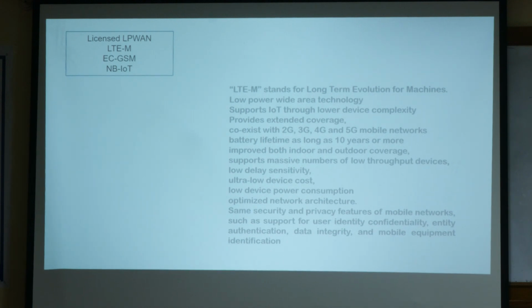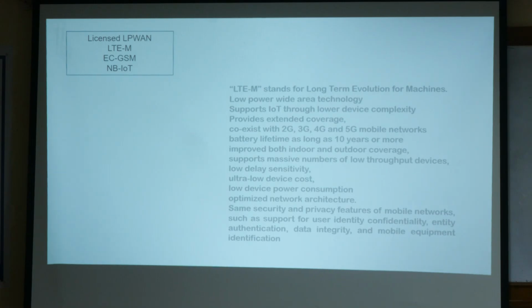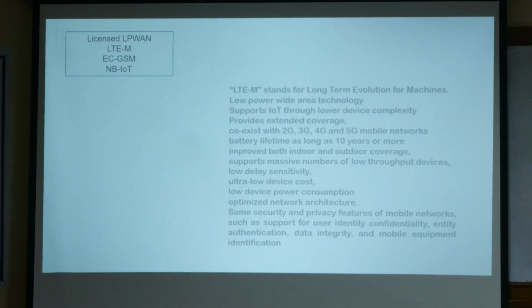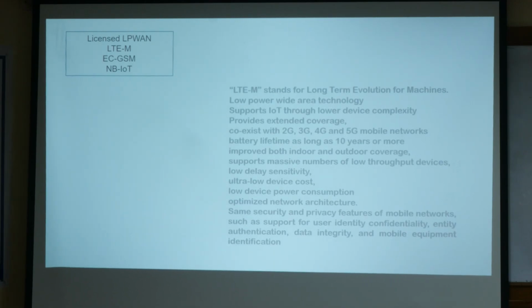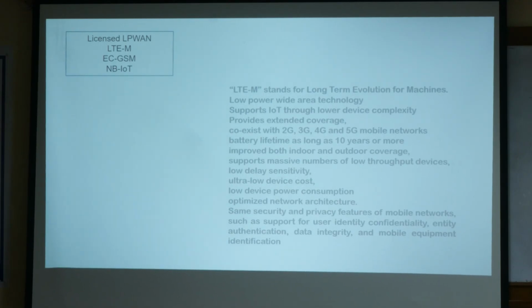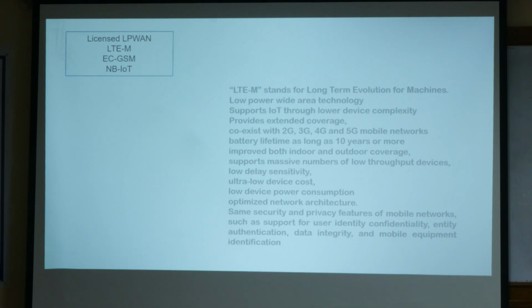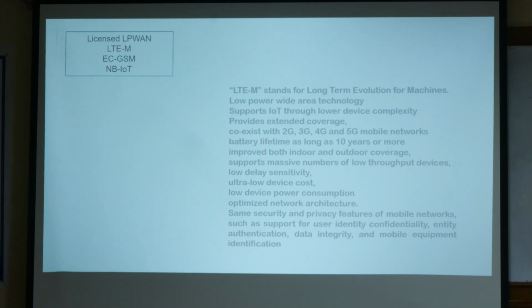The only thing is we are trying to see the low energy communication, and here the important thing is how we know what is the energy used. We are saying low energy and all, but first of all, who tells the network that my house is so far away? So we have a dynamic algorithm where it tries to learn on its own. We call it a self-learning algorithm. It sends a test bit and gets back the response. Based on the signal strength of the response, it tries to adjust the power. It goes on adjusting until it gets the optimal value and uses that value for transporting the data.